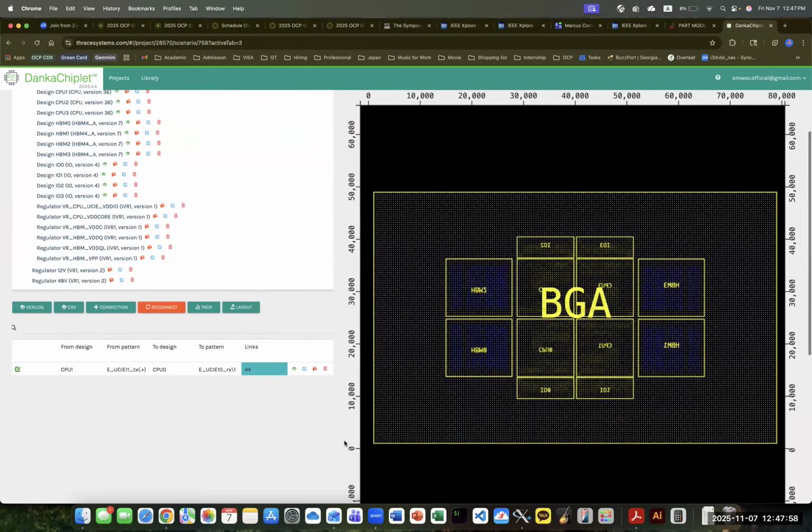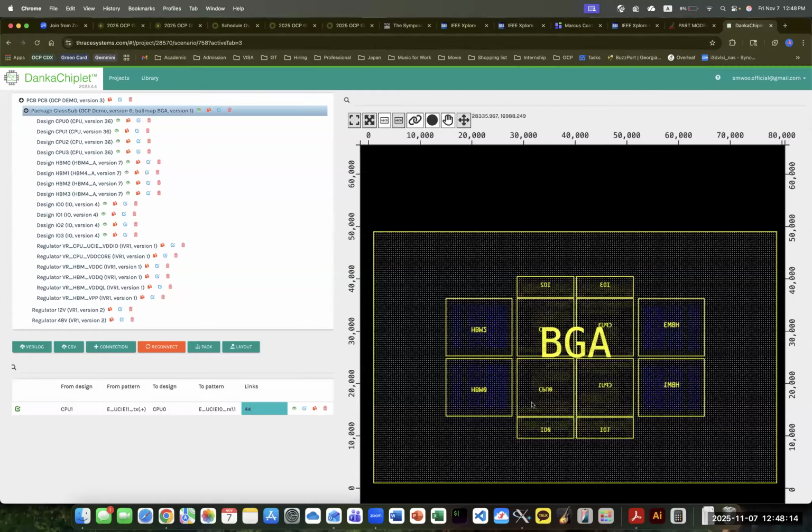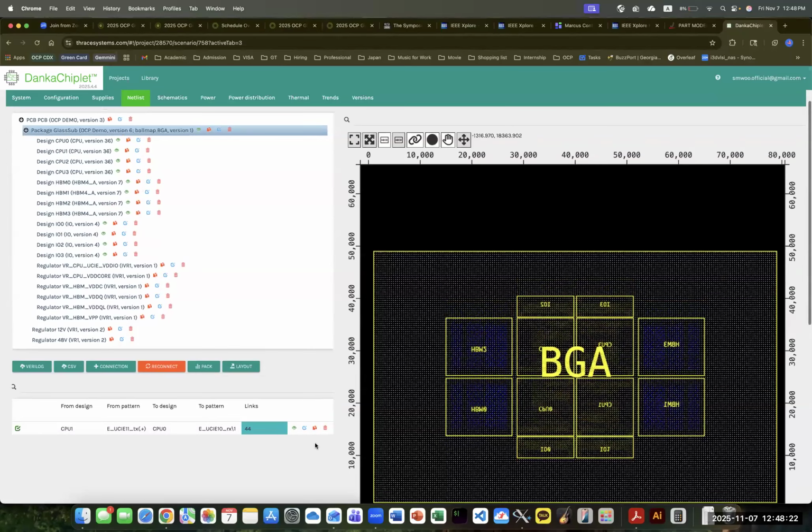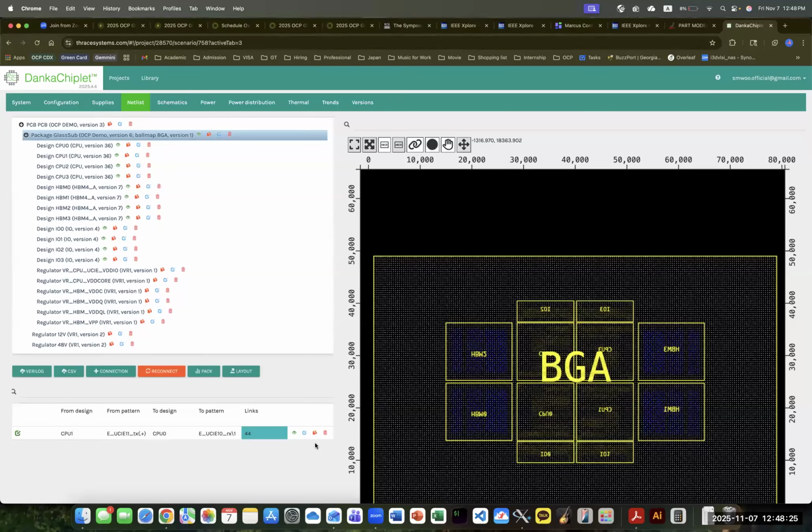Are those HBM4s? Is that what we decided to go with? Yes. We cannot go with anything else. Are those the actual sizes of HBMs? Yes. I'm sorry, the chiplets are 11 by 11, and the HBMs are 11 by 14. That's the HBM4 standard. Okay, this is not to scale then.